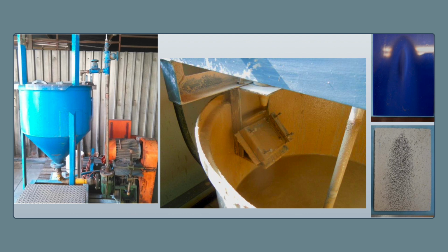The angle of the nozzle, sorry, I don't have a photograph of the nozzle here, but it was more at a 90-degree angle, and it gave us a deeper, more isolated type of wear, which we would see in some instances, maybe in a tube bend, or where the pipe diameter decreases, so we have that increased flow. But then we also looked at a different type of flow, which is the bottom sample, which was at a flatter angle, and represented more the drag or sliding type wear.